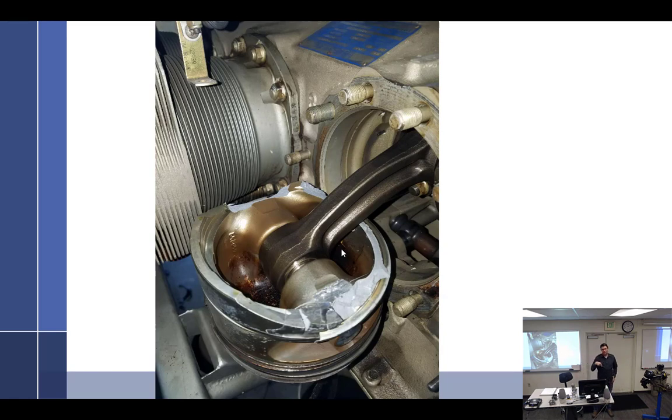And people have you do that with radials too, huh? Everybody with a radial engine does that. The bottom cylinders fill full of oil all on their own. And if they hit the starter, and some of these radials don't start like you think they do, where you turn the key and the starter comes out and grabs it and starts to go. They have inertia starters, where you spin up the inertia and it gets going, and then you pull a lug and it goes whack, and it grabs onto a gear and starts spinning it. The starter's already going like 1,000 RPM, and the engine's got to catch up, and so there's no hope if you have a hydraulic lock.